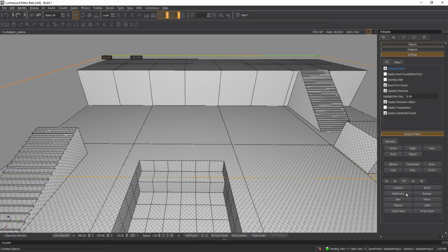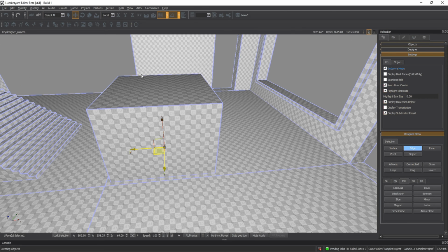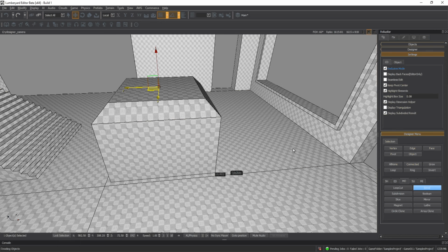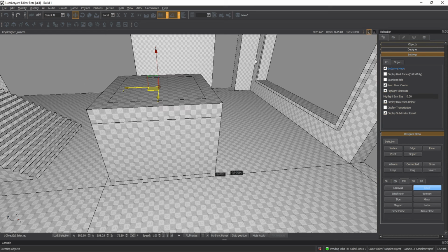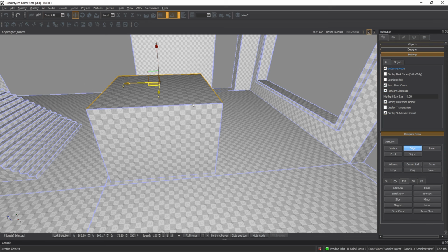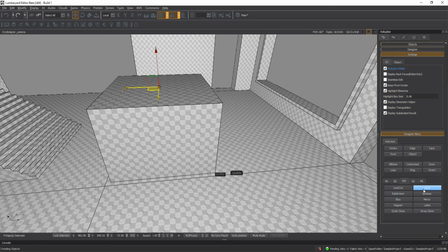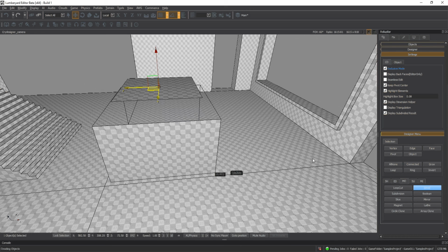There are a lot of options in here. Your bevel options, select your edges. Going to edge mode, hold control to select multiple. Add in your bevels, select the depth of your bevel. How many faces? Now the first time that you do this, it works a little weird because you select bevel and then you're not actually inputting values anywhere. Moving your mouse up and down will create the effect that you're going for.